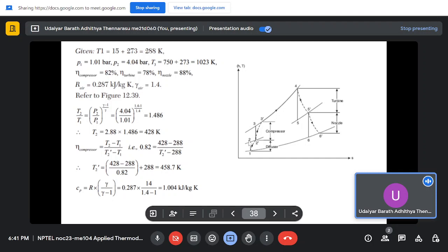So 1 2 it will happen isentropically, but in this case instead of 1 2 it will be 1 2 dash. And then with the compressor there is a compression ratio of 5.8. So the compressor ideally should be 2 dash 3, but compressor also has an efficiency of 0.9. So we'll follow path 2 dash 3 dash, and then at state 4 the energy, this is at temperature 1110.